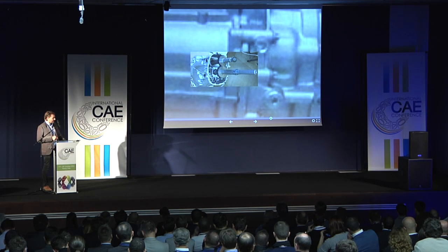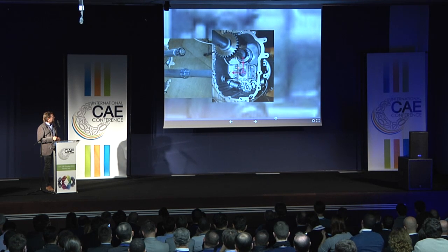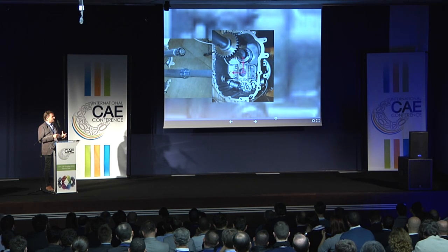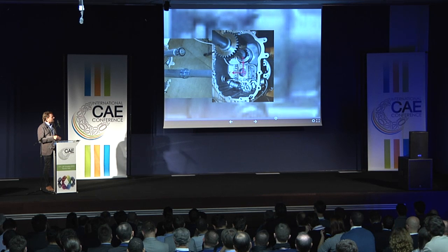To get a closer look, let me remove this shaft. So now you see this block of steel. It was the yellow one in the multi-body simulation model. So this block of steel sits in the original bearing seat of the gearbox housing. It is a press fit and is connected to the gearbox housing. These little things here are mini piezoelectric force sensors, and every sensor can record the dynamic bearing force in 3 directions.